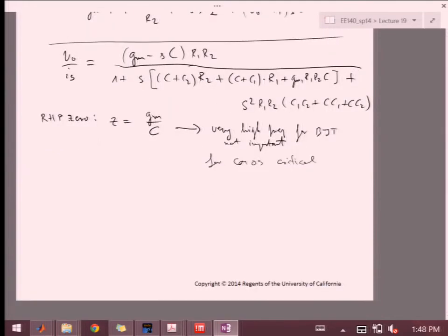Okay, but for now, because this is a bipolar example that we're talking about, we're going to neglect it. So at the end of the day, if you look at any polynomial of this form, you get 1 minus s times the sum of the 2 poles, plus s squared over p1 p2. So we're going to use these identities to look into these expressions for the s squared and s terms, and then read out pole 1 and pole 2.